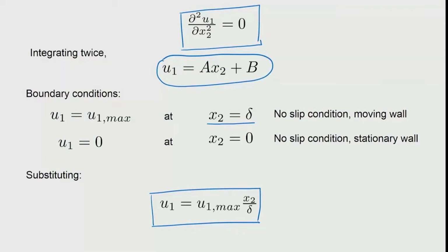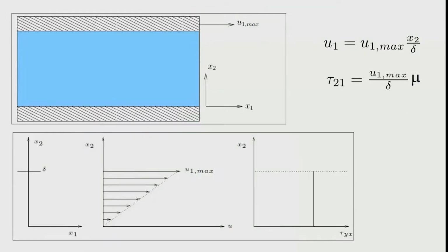So, this is a solution which gives you a straight line profile, which is the simplest profile that is possible for any solution of Navier-Stokes equation. Okay. So, we see this plot, the plot actually shows you that it is a straight line. So, here I am marking the profile of the velocity u1, okay, as a function of x2 or y.